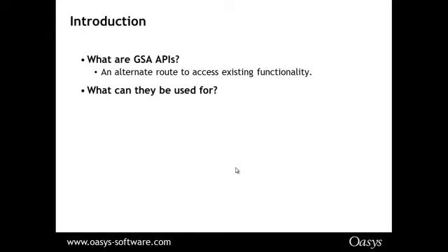They can be used for, in fact, anything that you want to do interactively within GSA. So sculpting models, extracting results. You can extract steel utilizations, create your own program for sizing members on the basis of steel utilization results, and also change member sizes iteratively. It can be used for creating plugins to 3D modeling packages like Revit or Rhino that export or import a GSA model into the 3D modeling package.